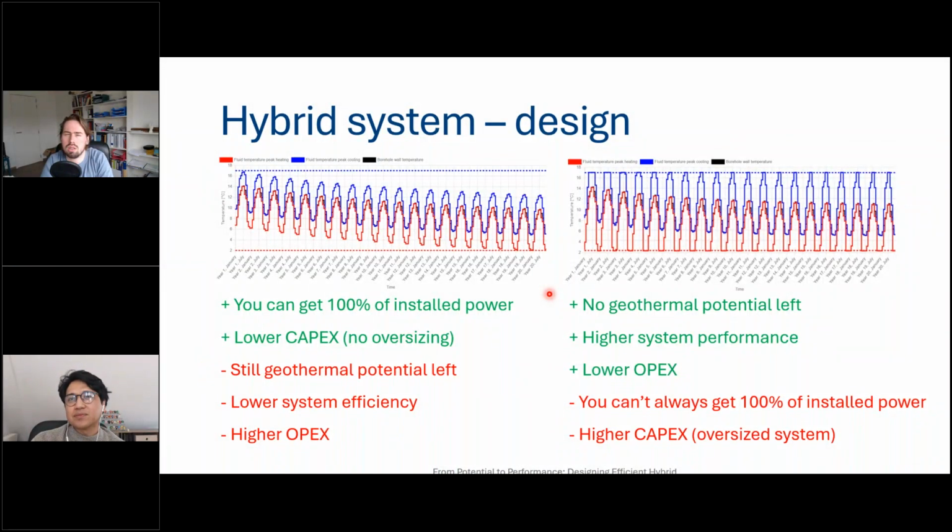It's difficult to say in general. Let me think about it. I don't think so, because in practice, when you optimize for energy, you will have a control strategy that says, well, the temperature is below our limit, we will put it onto our hybrid system. And the same you will have when you design it to optimize for power. The inherent difference is that in the first years, you cannot extract more heat from the ground because you're limited by the power.